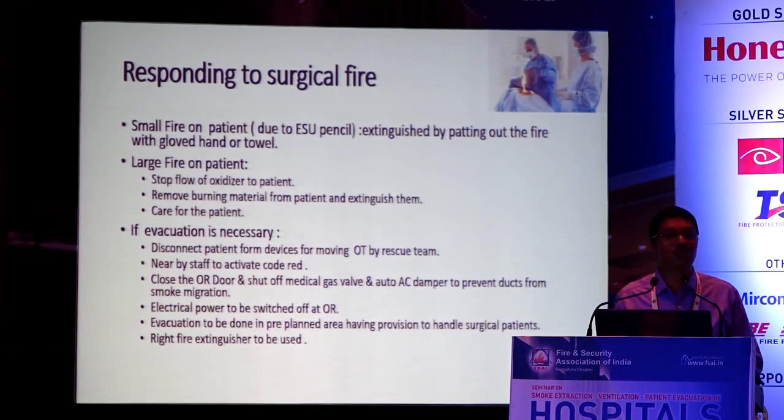Then close the OR door, shut off the medical gas valves, shut the AC damper to prevent smoke migration through the ducts, and switch off electrical power. Then evacuation is to be done to a pre-planned area having provision to handle surgical patients. The right fire extinguisher should be used. So these are some of the steps which are needed for the evacuation.